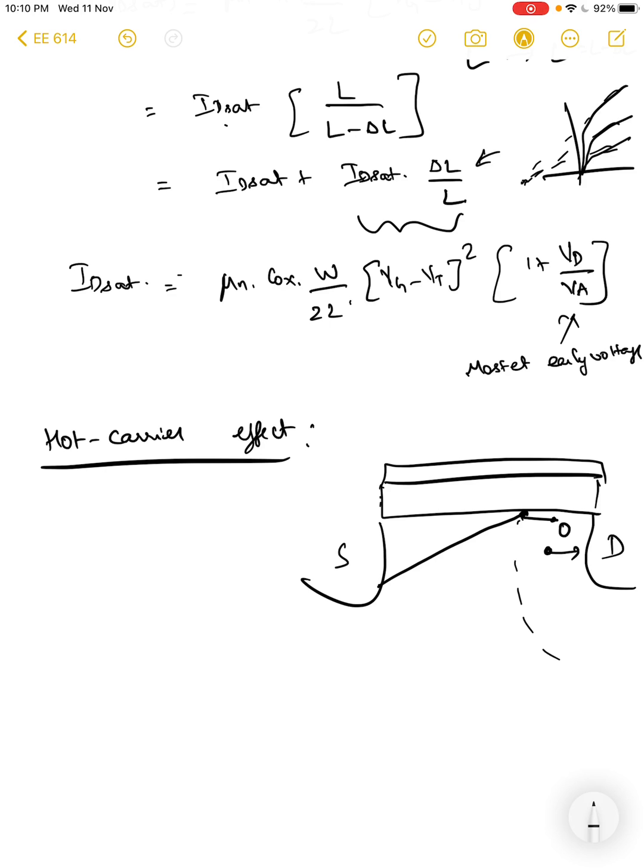So the electron is accelerated towards the drain, causing the drain current, but then the hole can be accelerated towards the source, right, because of the potential that you have applied, or it can be sunk to the body because both of them are at equipotential, and depending upon the body resistance here, the hole can be sunk down.